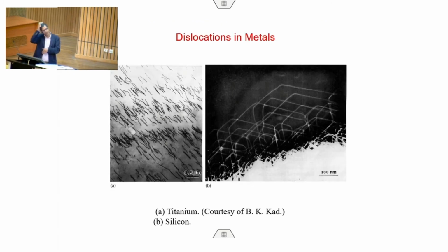Well, how do dislocations look in real materials? Let us discuss this for say 10 minutes or so, and then we can stop this lecture. Well, dislocations cannot be seen by any technique other than TEM actually. An idea can be obtained by different kinds of microscopic techniques, but transmission electron microscopy is the only technique by which you can visualize a dislocation. That is why it took some time to see that.